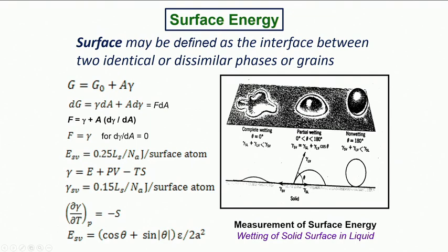So for example, in a situation where an incoming droplet does not wet at all, we now realize that the wetting angle or the contact angle is practically 180 degrees, because there is only a point contact between the droplet and the solid underneath. So in a situation like this, the solid will not get wetted by any such incoming droplets.